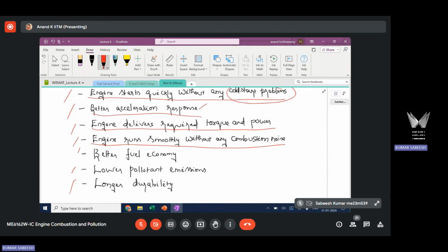So we have already discussed how the combustion noise will be affected by the molecular structure of hydrocarbons present in gasoline and diesel. So these legal agencies will ensure that the fuel has the required quality so that the engine runs smoothly without any noise. For example, in a CI engine, if the delay time is more, you're going to get more noise, meaning it should have the required cetane number. It cannot be too low. It will lead to high noise. So this is what they are checking.